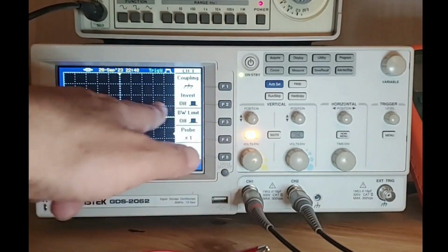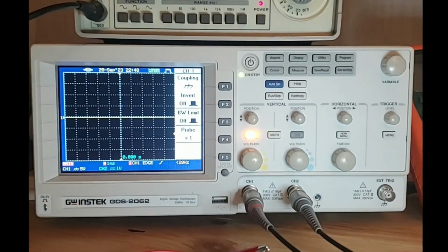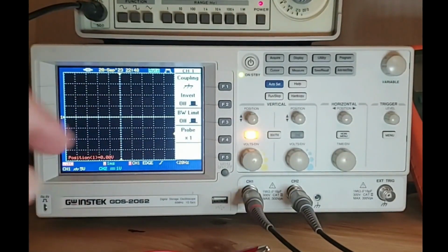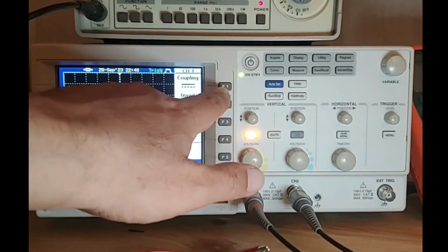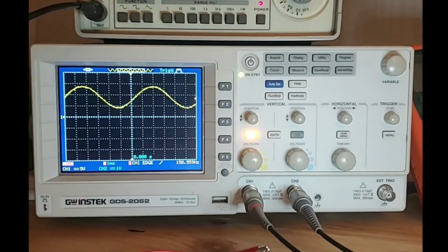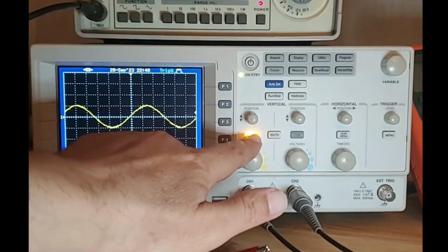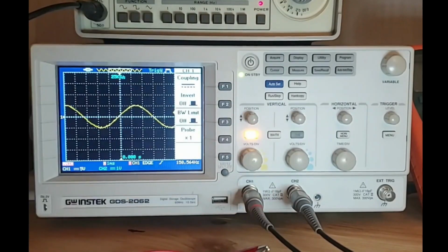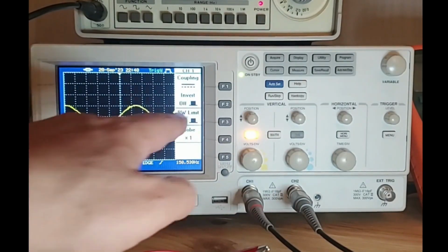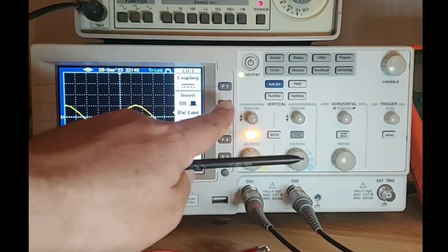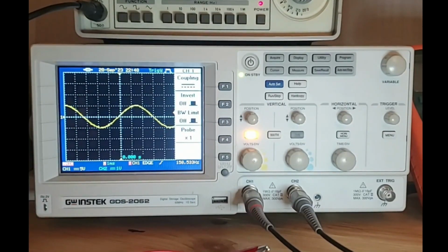The third option is ground. The ground is just that the probe is actually not going to show you anything. The scope will just show you the ground level. And it is useful so that you can adjust your ground properly. The position is 0.00. So that's for the ground and DC coupled. I will remove this for now. Now I want to get rid of the DC offset, so I will bring the waveform back to the original position. We saw inversion. If I want to invert the signal, I can press this option over here, and now you see the signal is inverted. Or if I don't want to invert it, I can turn it off.